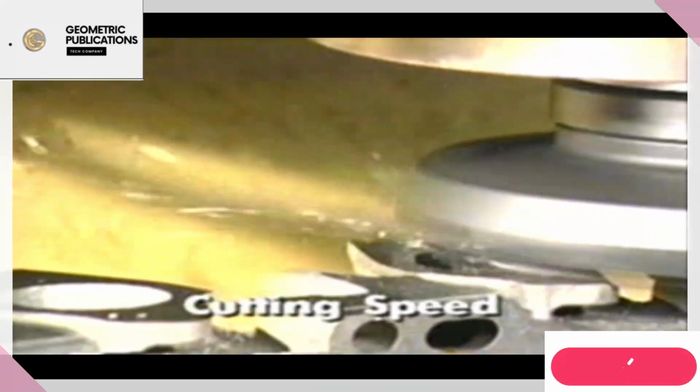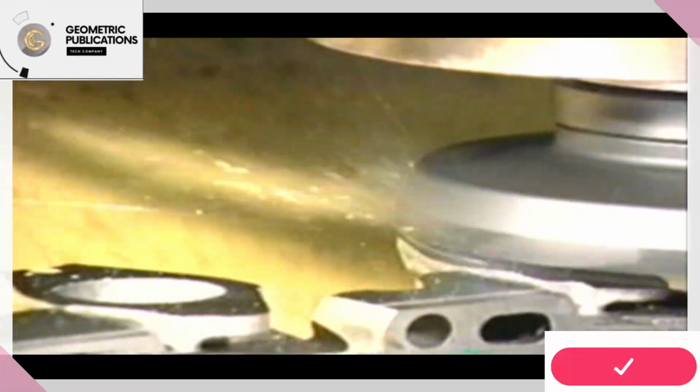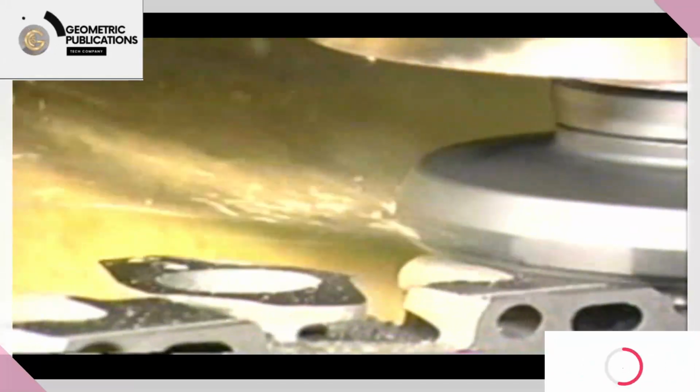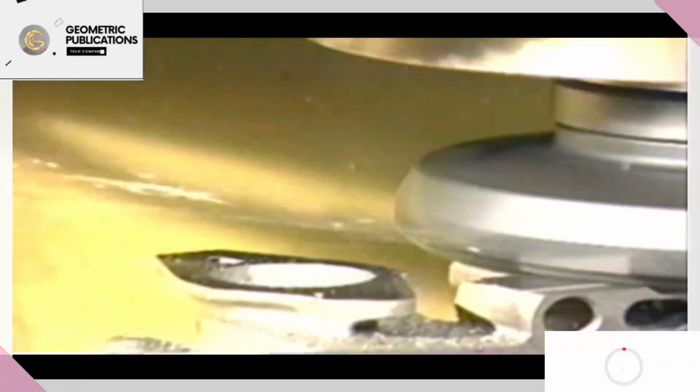In milling, the cutting speed is measured in terms of surface feet per minute. This is how fast the edge of the tooth at the periphery of the cutter enters the work. It is a function of cutter diameter and spindle rotations per minute. Typical values for common materials may range from 40 to 1,000 surface feet per minute.